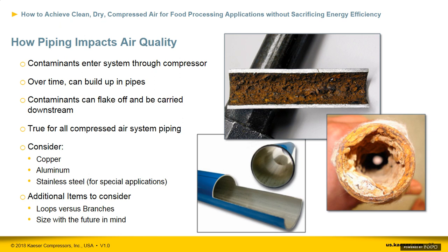Okay, so let's come to our final point, and this is true for systems with oil-free or oil-injected compressors. Don't forget the piping. I have seen this too many times. The plants spend time and energy selecting, purchasing, and installing a bevy of compressed air treatment only to have the clean, dry air pass into an old, dirty piping system.